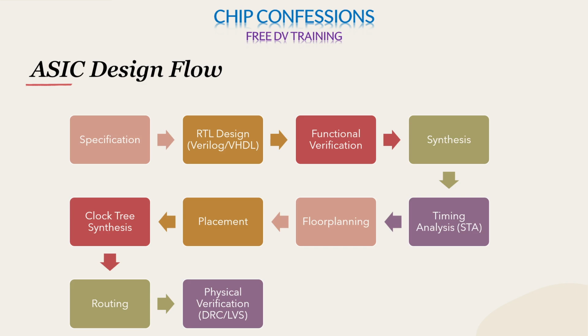We should ensure that the correct number of transistors are placed, the correct number of gates are there, the proper connections are there between them, and they have proper matching names and proper matching pins. All that will be checked in layout versus schematic, the LVS stage. This ensures the layout is matching the exact logical design and is complying with the manufacturing rules.